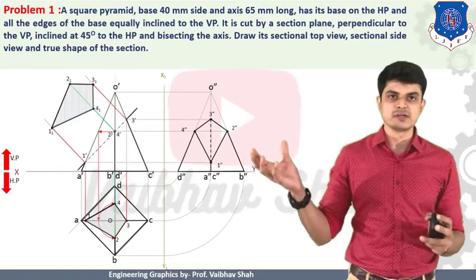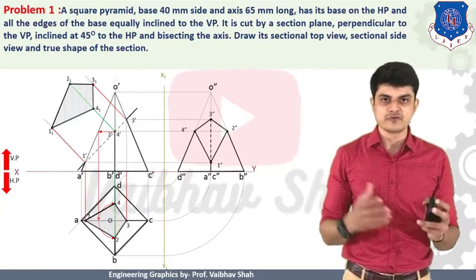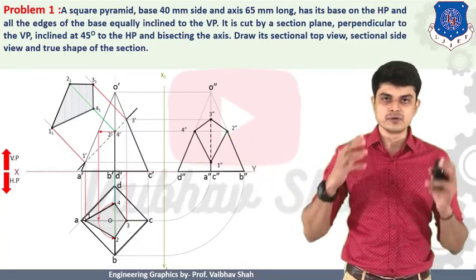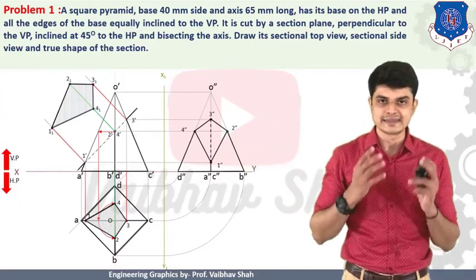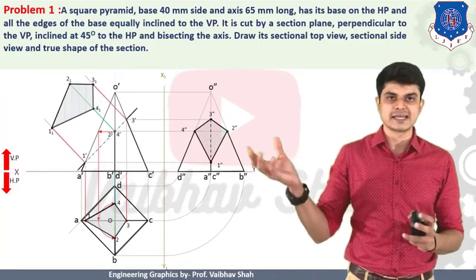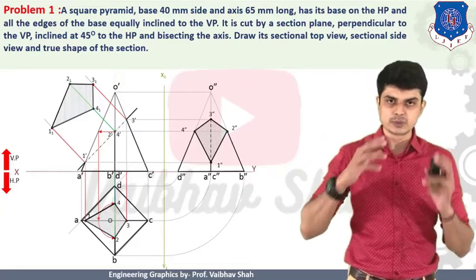Now we should define the hidden line. As we can see, we are taking the side view from the left hand side direction of your front view, so the line 3C would not be visible in our case, so we should make this line a dotted line. And as it is a cut section, you should specify the section cutting line on this section. So this is nothing but a section shown in your side view.